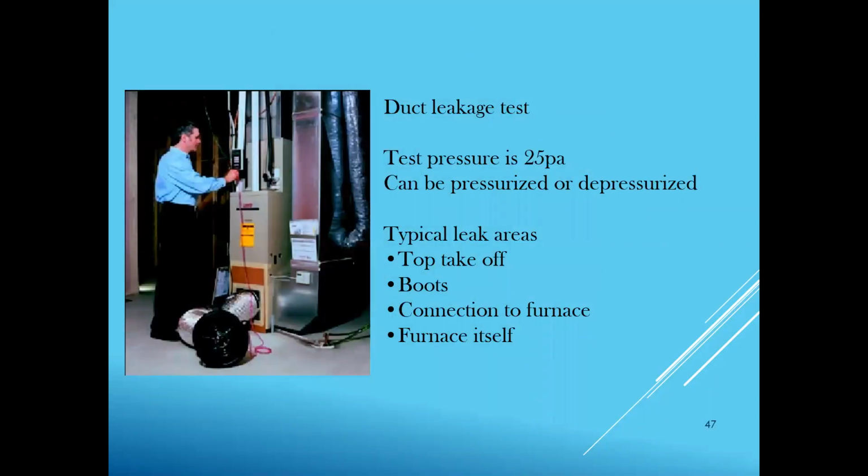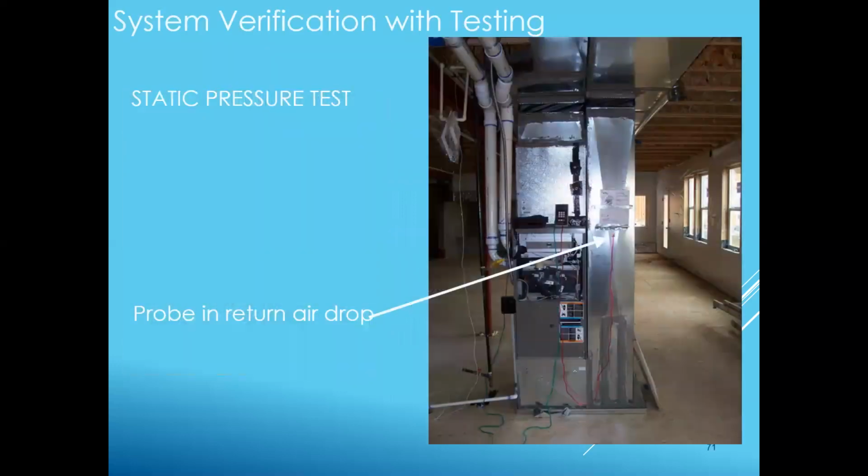Duct testing is a piece of cake. Not hard to do at all. But it is not required unless some of either the furnace or any of the ductwork itself is located outside the building thermal envelope. If none of that, then you don't have to test it. I encourage everybody to test their ductwork for total duct leakage, but it's not required.